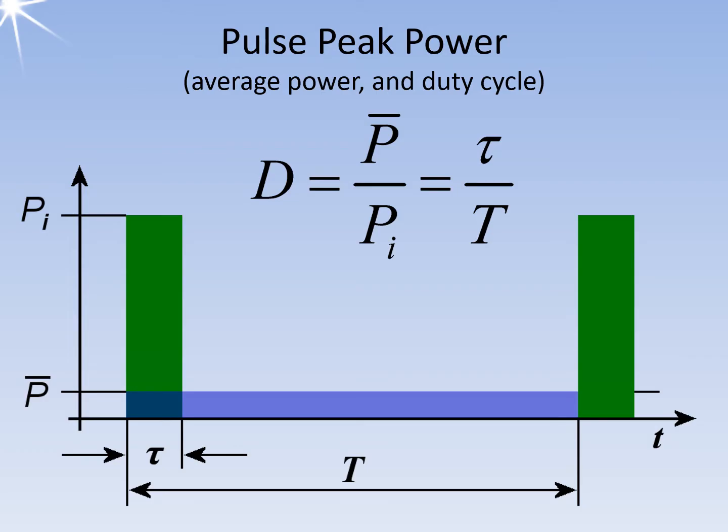The transmitter's pulse determines not only the range of a classical radar but also the range resolution. Therefore, it should be as large as possible, for good range, but as short as possible, for good range resolution. These two requirements can usually only be realized with high-performance transmitter tubes: magnetrons, klystrons, or traveling wave tubes.